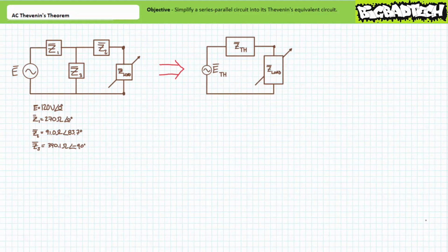The original complicated circuit and the Thevenin's equivalent should ideally behave the same, and importantly, the load impedance should be none the wiser to the substitution. Of note is not only the substantial ease with which calculations can be made using the Thevenin equivalent circuit, but also how much fewer components, connections, and confusion is involved with the physical construction of the Thevenin's equivalent circuit.